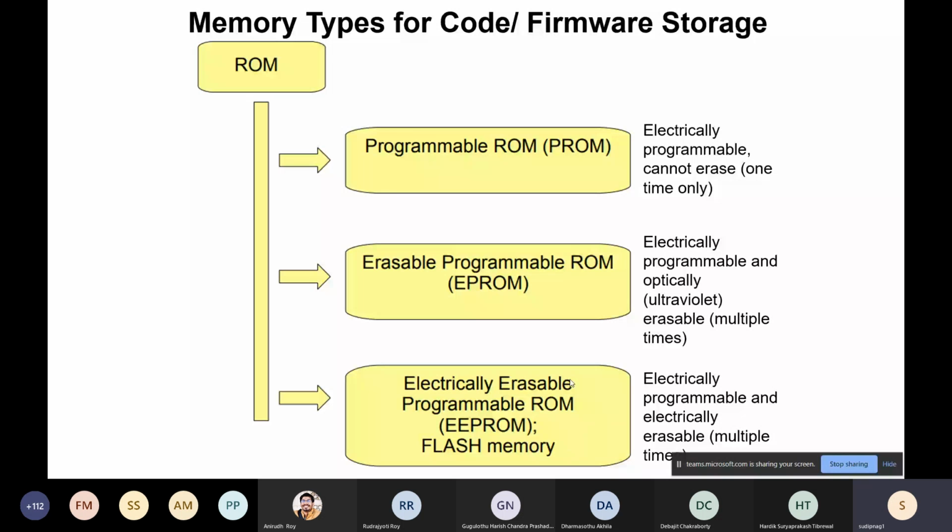But the EEPROM is typically used to store user data, for example, something that you will refer to many times. But flash memory, as you said, is mainly used for code storage. Now, the endurance of these two types of memories depends on the fabrication strategy. If you look at the datasheet, they must have said about the endurance, like 1 million cycles for EEPROM,